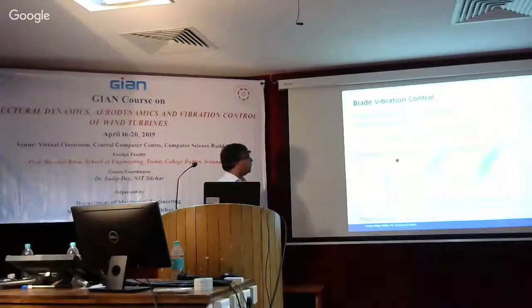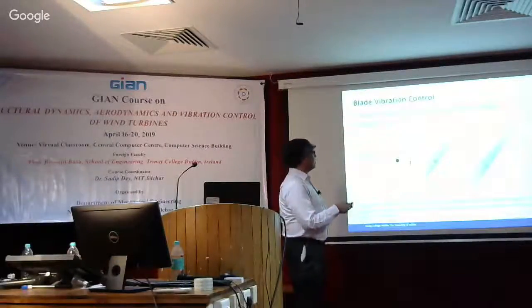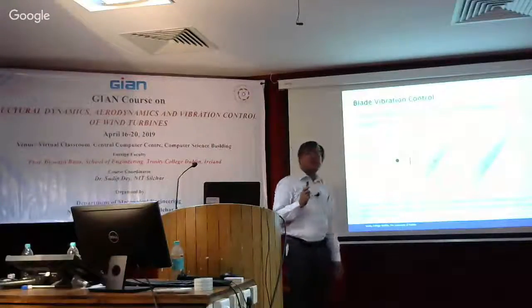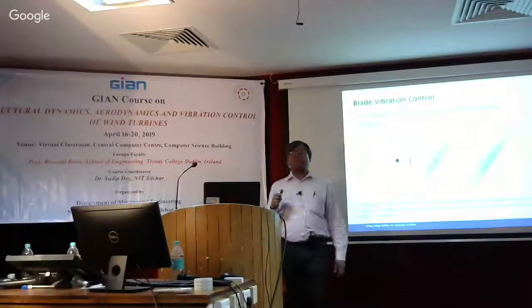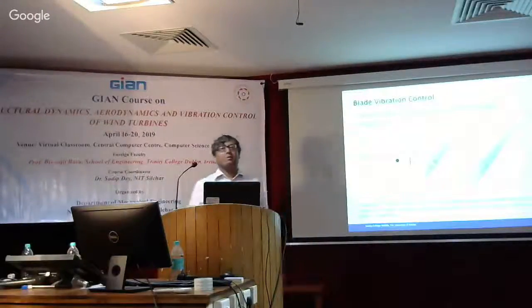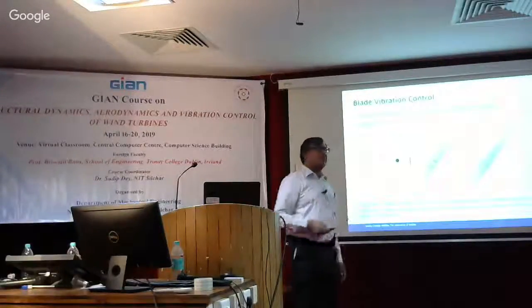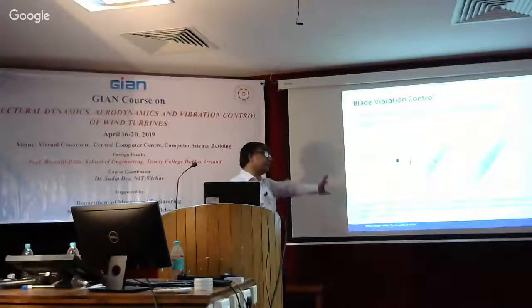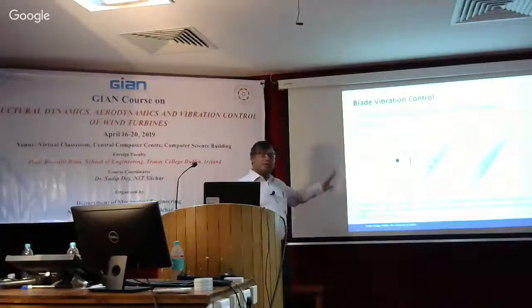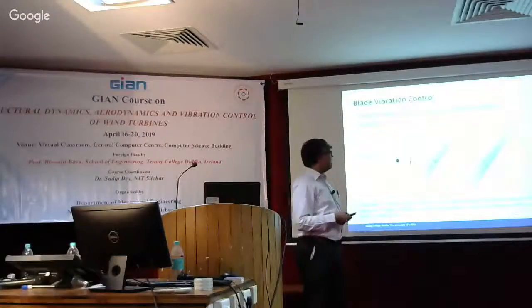So it's a figure showing the active tuned mass damper with cable connection here. So now you have a tuned mass damper, a spring and dashpot here. Now there's also one advantage for a liquid damper: you don't have to put a dashpot inside. And the blade manufacturers don't like a dashpot because there'll be a maintenance issue. You have to replace the dashpot, and you rely on the dashpot for the tuned mass damper. Then you have to bring down the blade, and that's not easy. That's why these sort of devices are not very well preferred, and that's why they prefer to go with liquid dampers.